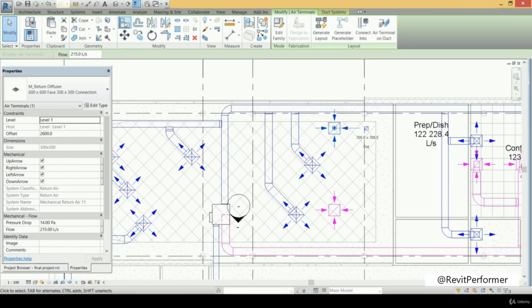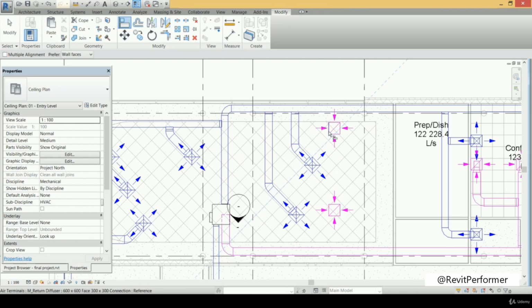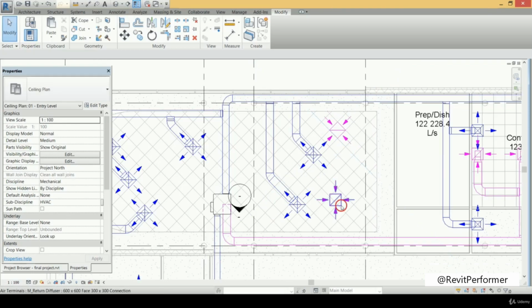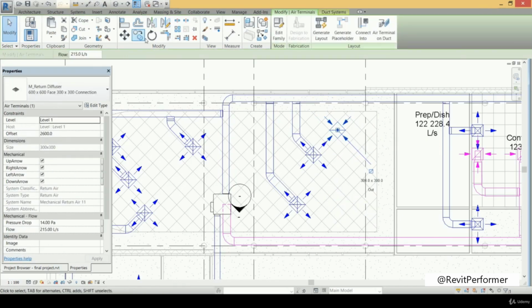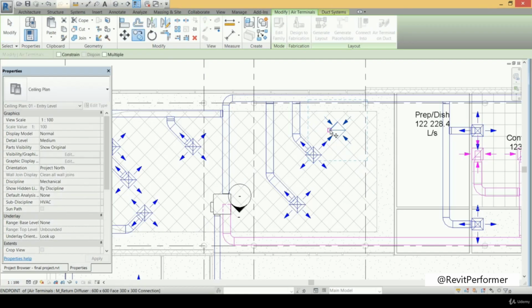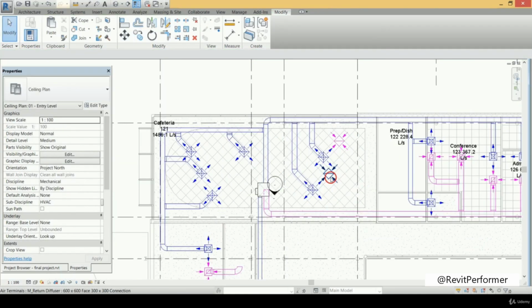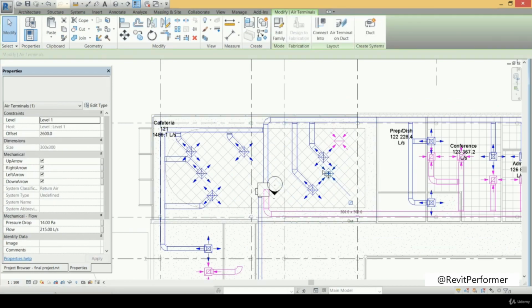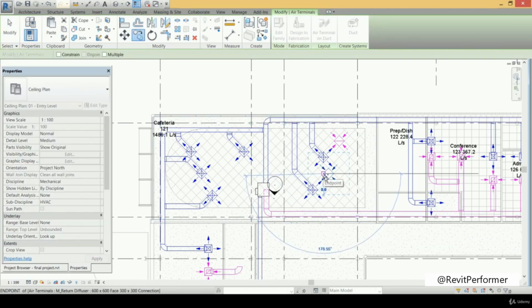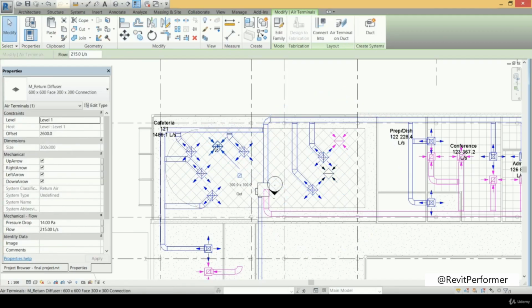And then we can align that air terminal here with that slab, for example. So we press on align and then that edge with that air terminal edge. Here that one, and then the decline edge with that decline edge of the air terminal. And we will delete that air terminal. We don't need it. And then copy that one. So we press copy and start picking it from that point, and then we paste it at that point, and then we select that one again and press copy, and we pick it from that point, and then we can insert it at that position, and also we can copy it.